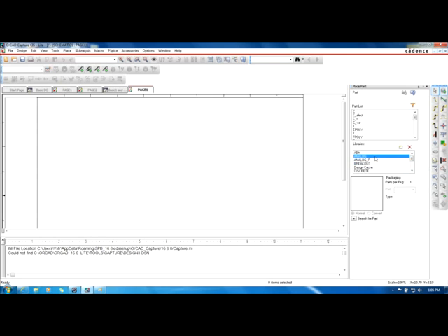I forget what they call it. But here's the ones that work on the simulator. Analog, analog P right there. Matter of fact, we'll go through the parts list that analog has. If you notice down here where I have the mouse cursor, it has layout and it has PSPICE. That's telling you that it will work on the simulator.